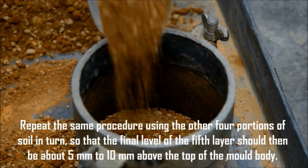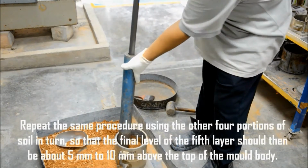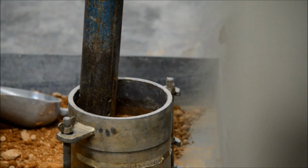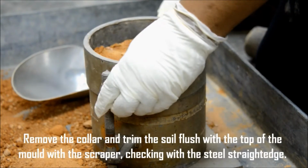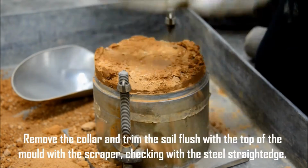Repeat the same procedure, using the other 4 portions of soil in turn, so that the final level of the 5th layer should then be about 5 mm to 10 mm above the top of the mold body. Remove the collar and trim the soil flush with the top of the mold with the scraper, checking with the steel straightedge.